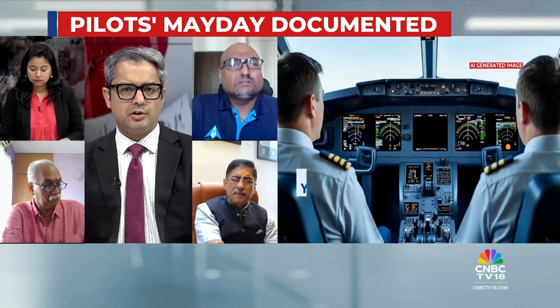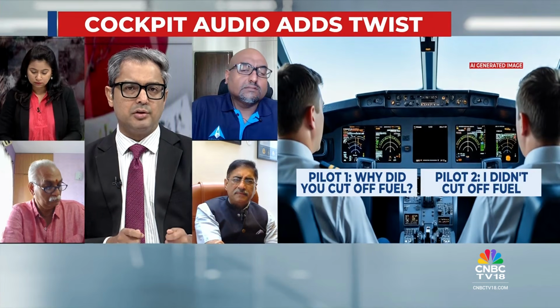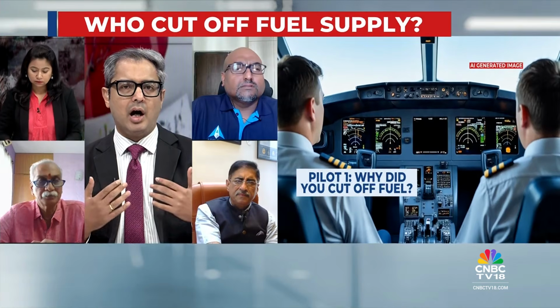Mr. Martin, so from this 15-page report, what we do know is that the fuel control switches were in cutoff position. They should have been in run position. The pilots realize it, and they pull both back into the run position. One of the engines gets relit. The second one did not have enough time to get relit. And of course, the RAT had already been deployed, and the plane crashes.